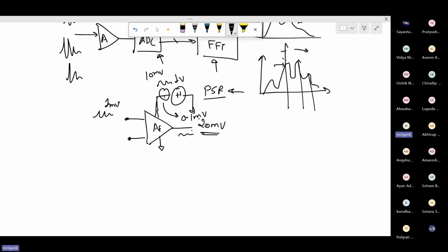That part you can check, and that will help us decide whether an LDO is needed, because a more precise LDO will be needed if the signal is very small, very weak. Like suppose we have to handle sub-millivolt signals, 0.1 millivolt signals.